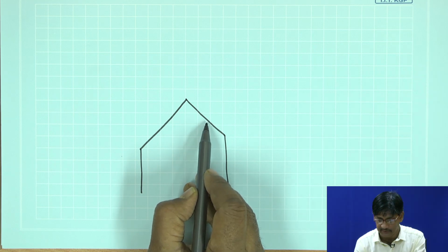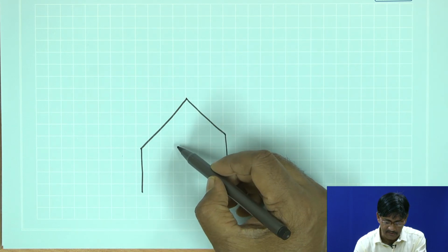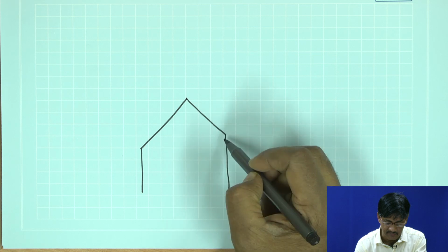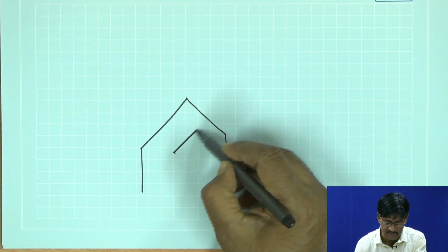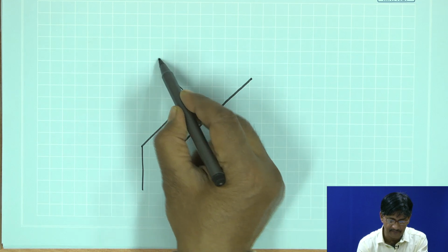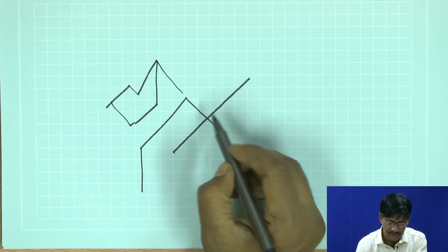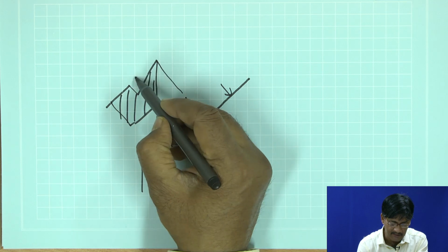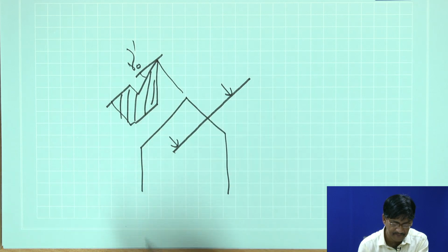Next, orthogonal rake. Orthogonal rake essentially means that we are cutting perpendicular to the reference plane and perpendicular to the cutting plane. So, this is the trace of the cutting plane, it can be seen only as an edge. So, cut it this way. If you cut it this way, we get this one as the section, and this angle happens to be the auxiliary orthogonal rake. Okay.